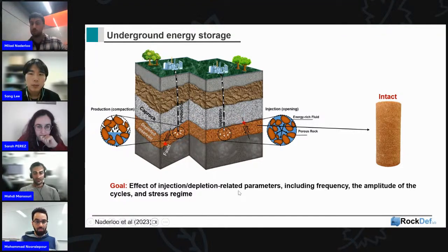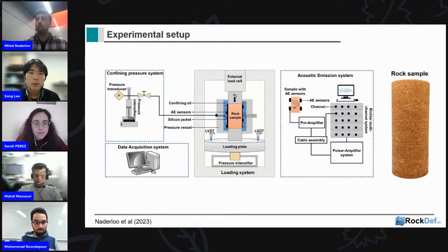In this research, we try to answer that. For that, of course, we need an experimental setup. This is our loading system, where we put this nice cylindrical Röt sandstone (Rotliegend formation) inside our pressure cell. We provide confining pressure with our ISCO pumps, and we provide sigma 1, the principal stress, with this loading machine.